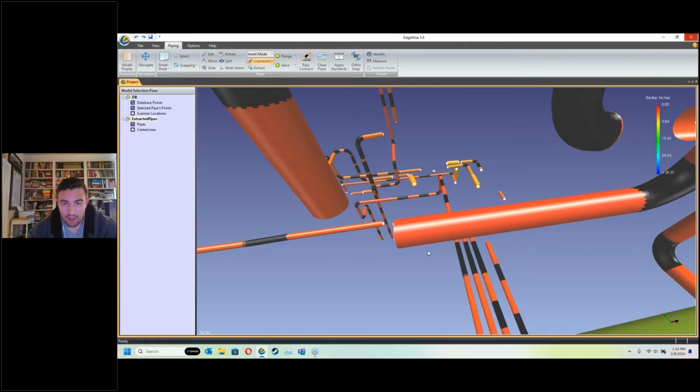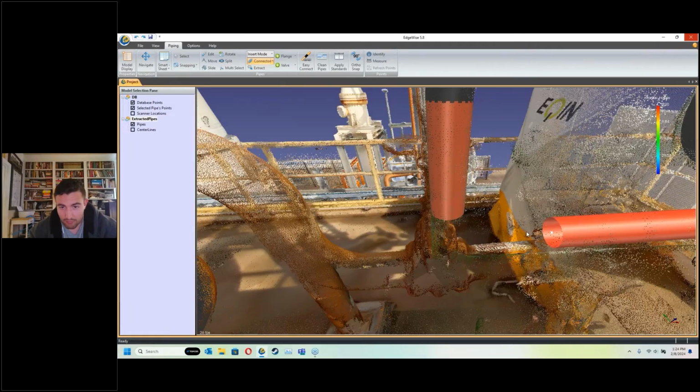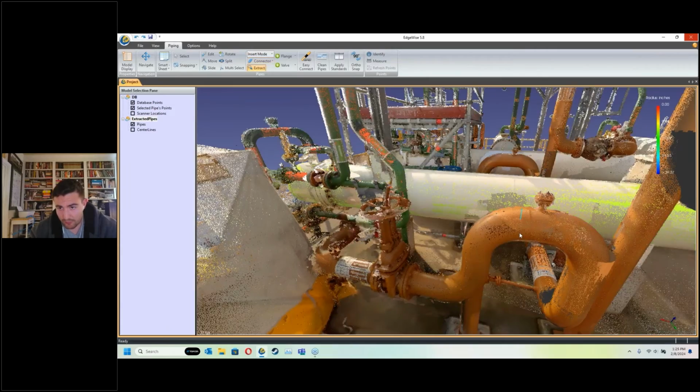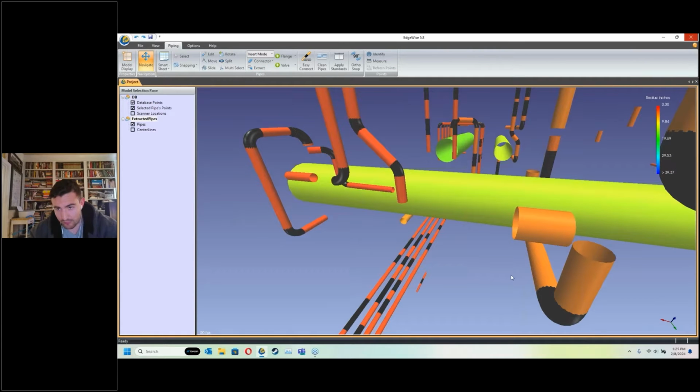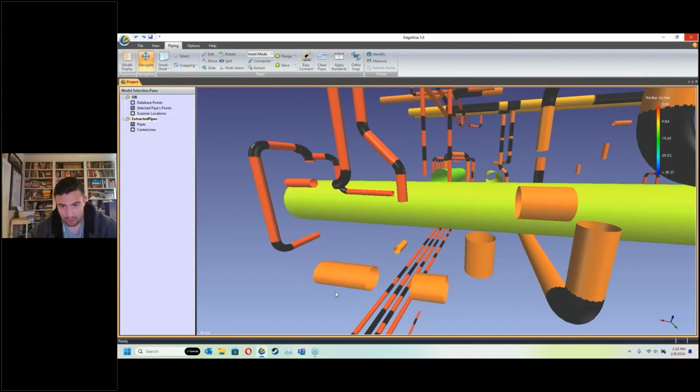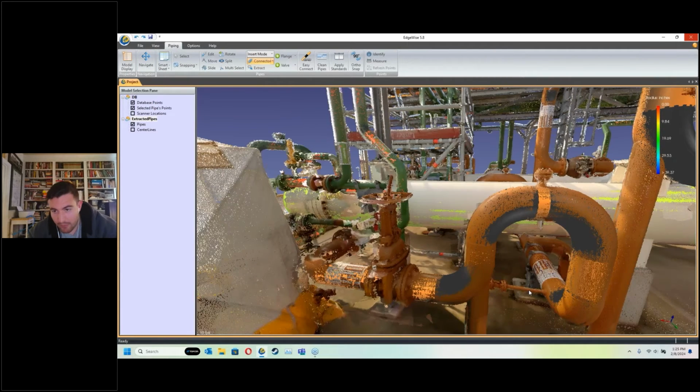Yeah, absolutely. So using survey control, you can basically expect a local accuracy of around 5 to 6 millimeters, and from a global accuracy aspect about 12 to 15 millimeters. And what I mean by local versus global, actually, Trevor, do you know what I mean by that between the two?